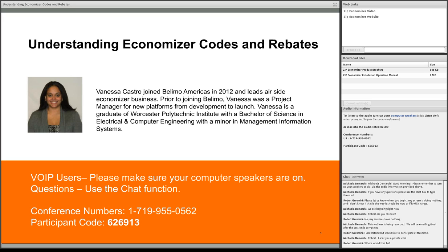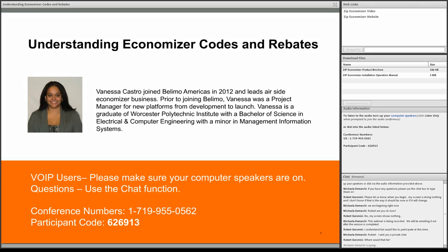Thanks, Michaela. That's actually a really good question. Based on my opinion, again, not knowing anything with what ASHRAE is doing internally, what we have seen is a continual growth or change to leveraging what has been done in previous years and expanding upon it. I think California has seen great success thus far with their new code implementations, which was done effective July 1st. And I can see a few of those requirements and changes being taken into account for the next round of ASHRAE changes, especially those pertinent to damper leakage and economizer high limit requirements.